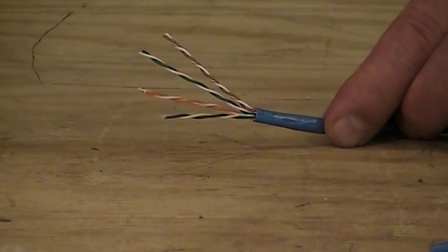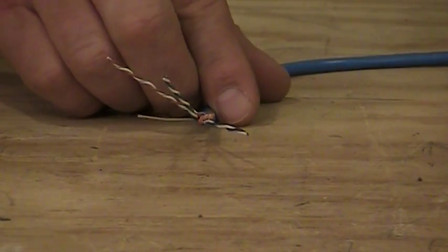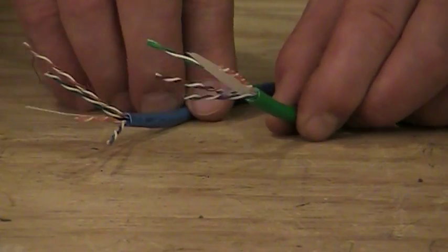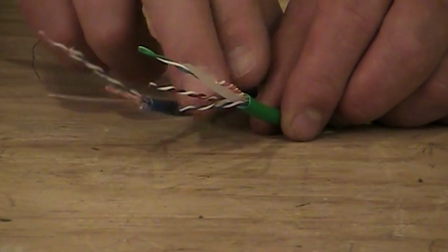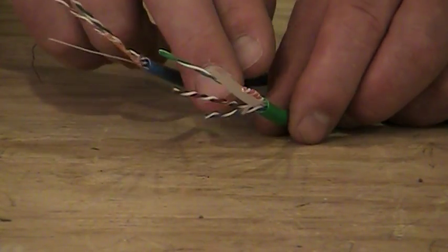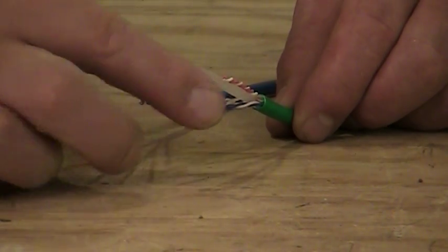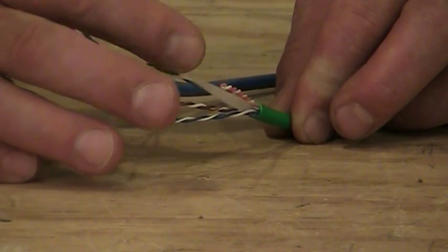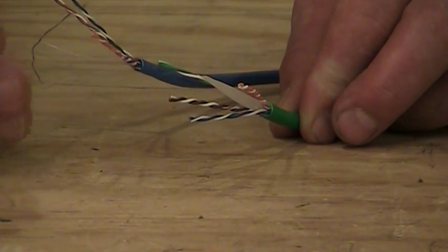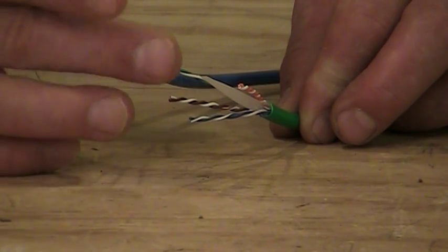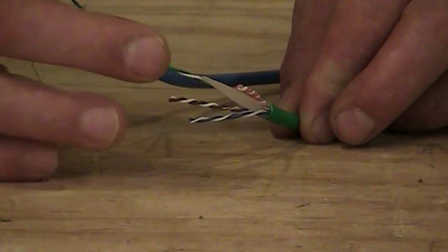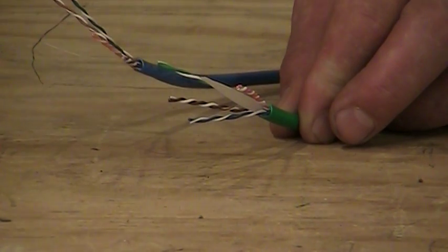Now, the next cable beyond that is category 6. When we look at 6, it's a little bit thicker in diameter, partly because the amount of twisting has been increased in the cabling. Also, besides having a nylon ripcord, we would also have some form of a separator. Not all 6 wire has separators in it, but a lot of it does. Some of it has larger plastic splines than this little tab you see here. But again, this is a representation of a typical category 6 wire you might see today.